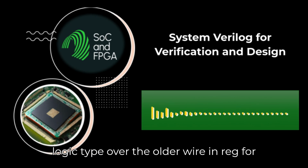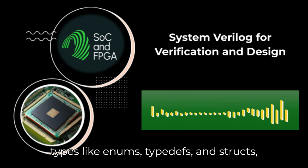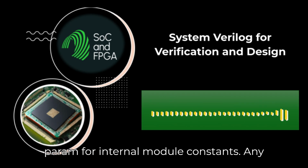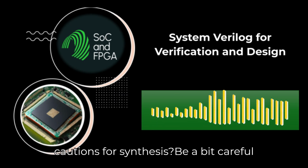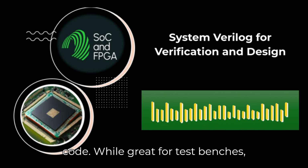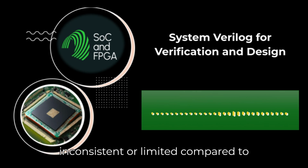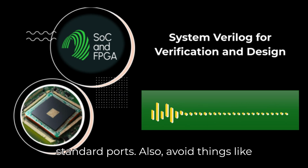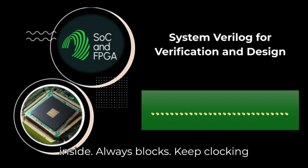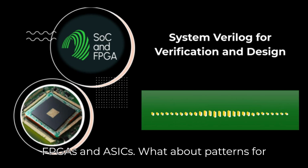Prefer using the logic type over the older wire and reg for consistency. Leverage the richer data types like enums, typedefs, and structs, especially packed structs, for better organization and readability. Use localparam for internal module constants. Any cautions for synthesis? Be a bit careful with interfaces directly in synthesizable code. While great for test benches, synthesis tool support for interfaces, especially complex ones, can sometimes be inconsistent or limited compared to standard ports. Also, avoid things like generating clocks or complex clock muxing inside always blocks. Keep clocking structures clean. Be mindful of initial values and declarations, as their synthesis behavior can differ between FPGAs and ASICs.